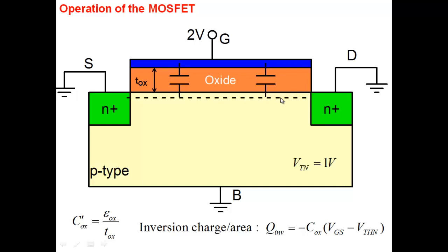When we are talking about a strong inversion layer, I'm talking about surface electron density of the order of 10 to the power 19, so 3 orders higher than that point. So we are talking about a very strong inversion layer here. All right, so this is the expression for how much inversion charge I have here. Now note that this is inversion charge per unit area.